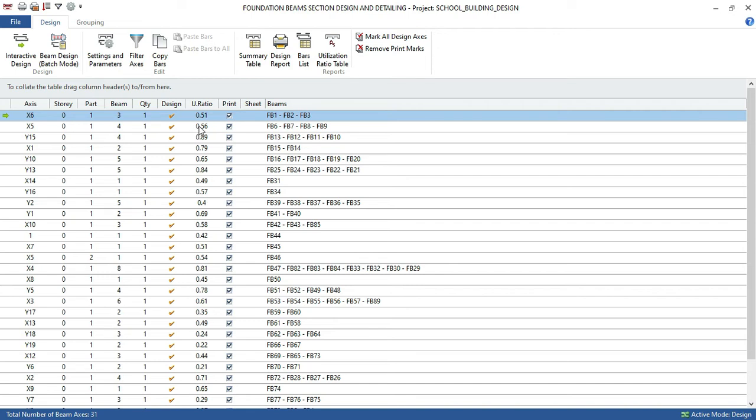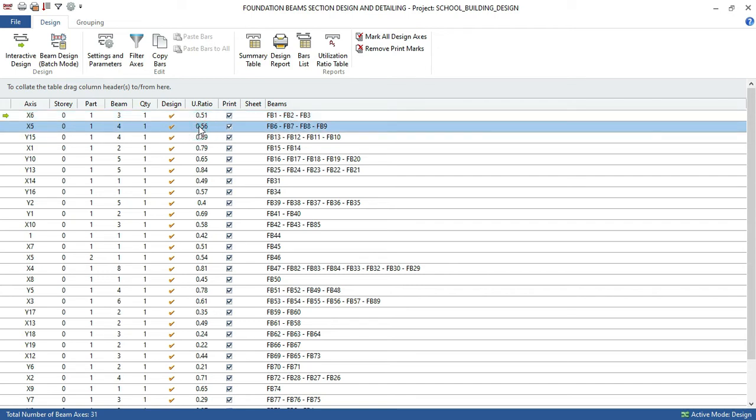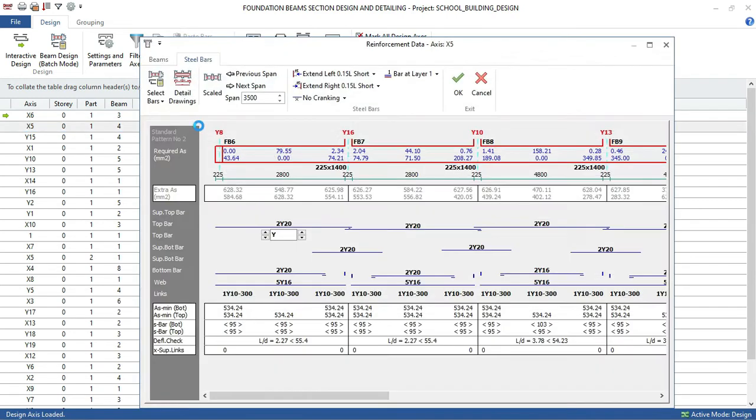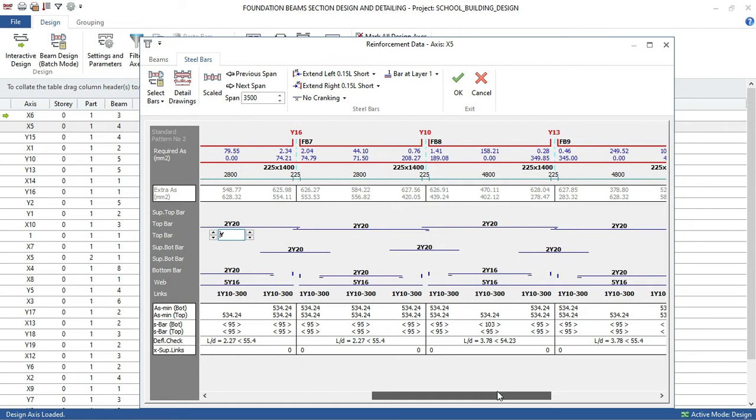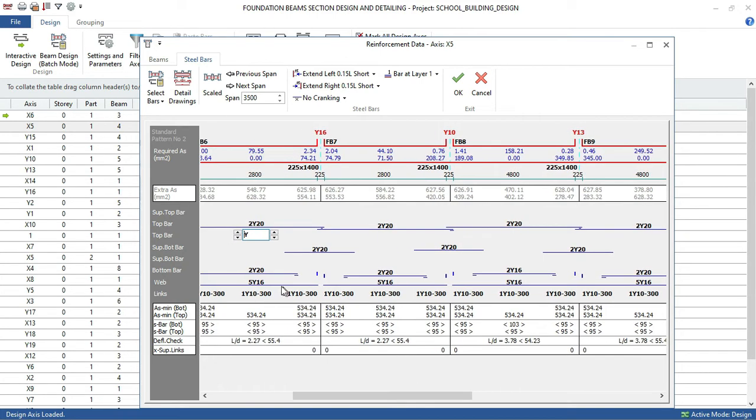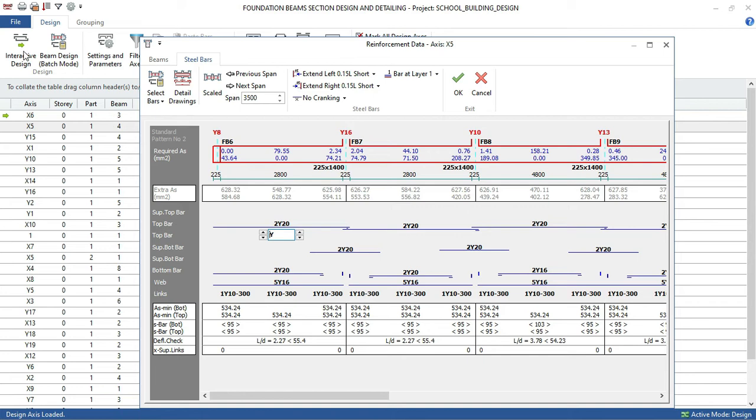So right now we check on this again. Always check the beams one by one to be sure what the beam reinforcement will be at the end of everything. If you export this right now as your beam result, you will see that all the reinforcements are not arranged. You see messed up detailing. So you have to arrange it by yourself. That's why it is called software. Someone programmed this, and those people also make mistakes.